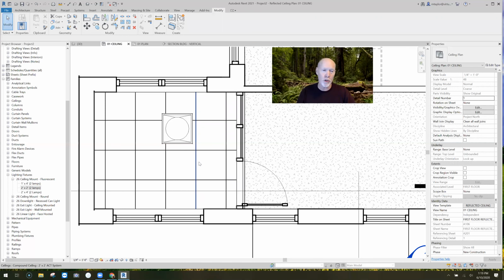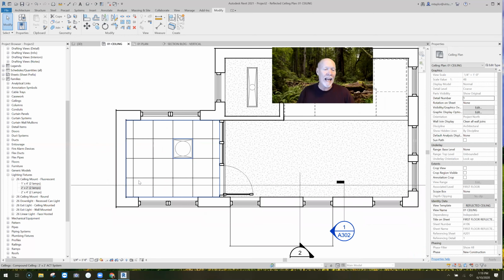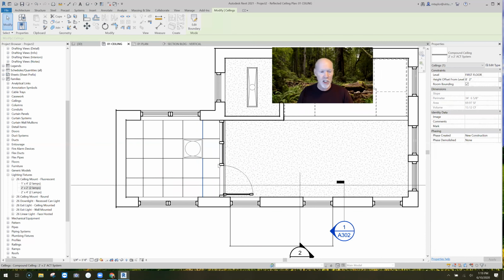So here's what I want you to do. After you place it, use align, AL on the keyboard. Go here, then here. Now the edge is aligned to that grid line. And if we were to move the grid, it stays locked in place. Like I can take this grid and MV on the keyboard, move it to the right, like 1 foot. I type 1 and hit enter. And it slides it over.